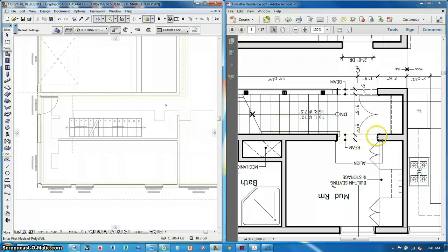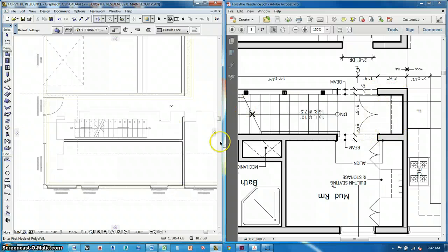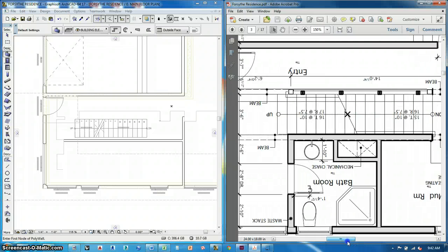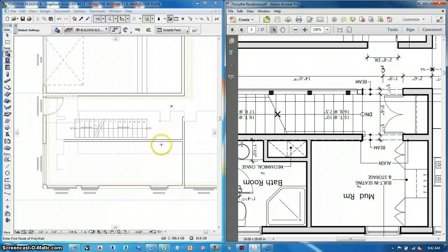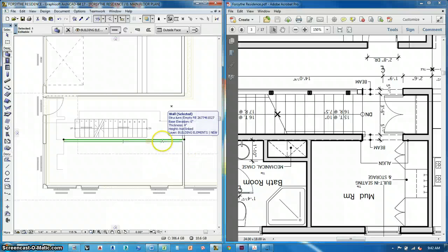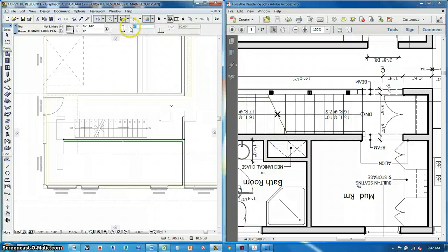And then, you know, this is a door that's inside of a wall, so I'm going to draw all of these as walls. And it looks like because they're using a 5.5-inch beam that they're doing this wall as a 5.5-inch wall. And I'm just going to do it that way, Mr. Oder, you and your 5.5-inch walls. And then I'm going to drag a copy of that wall.